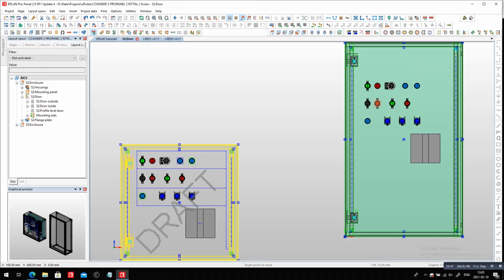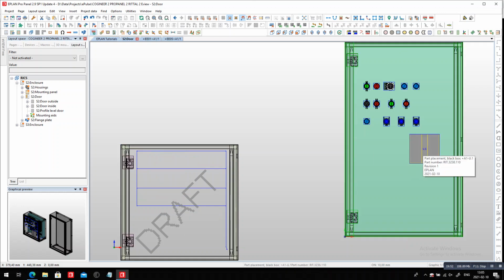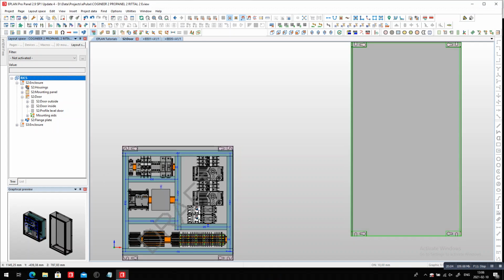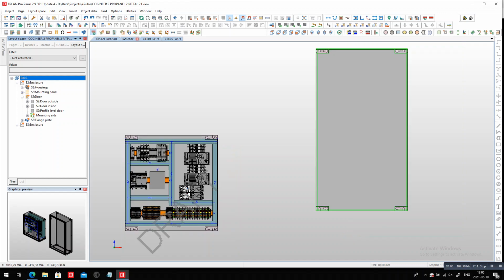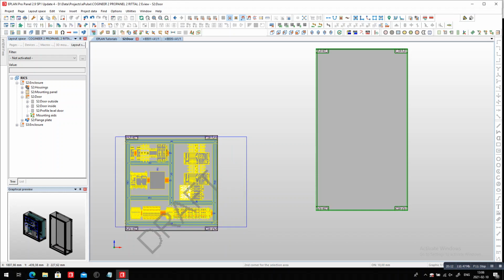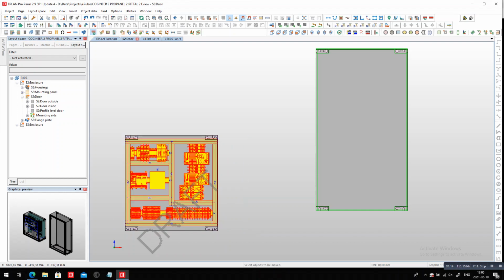Another thing that you can do once it's dropped over is move individual items to different spots. Like this one here, we could move it down to the very bottom here, no problem, to have better air circulation. So I'm going to do the same thing with the backplate. So show only backplates. And here I'm going to do the same thing. I'm going to pick very carefully in my selection just what's on the panel, not the panel itself. And I will just move it.